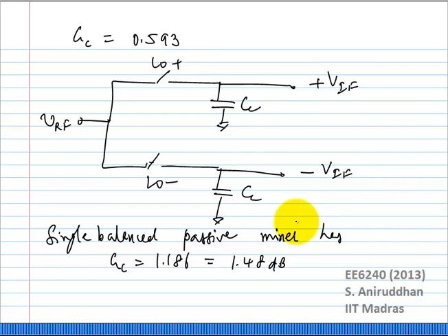Primarily it is because of that. Okay, because if you take a square wave, which is what you are driving the LO port with, the fundamental of that is actually larger than the amplitude of the square wave. Okay, so you can get a positive conversion gain. Okay, so we have looked at the single balance mixer for these two cases.